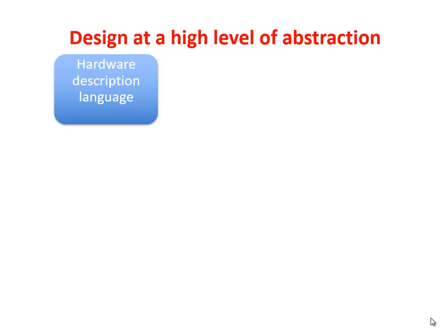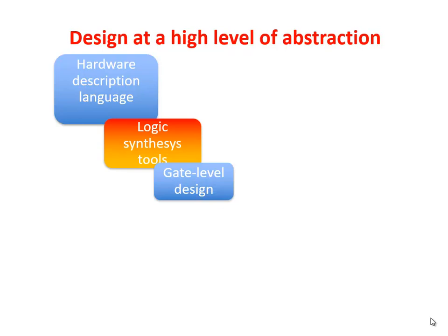One typically has the so-called logic synthesis tools that take as input the hardware description of a logic circuit, the description in Verilog and VHDL, which are the languages for hardware description of circuits, and translate it into a design at the gate level, a circuit consisting of logic gates.